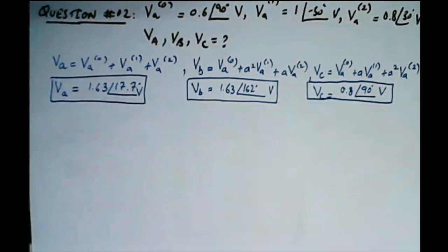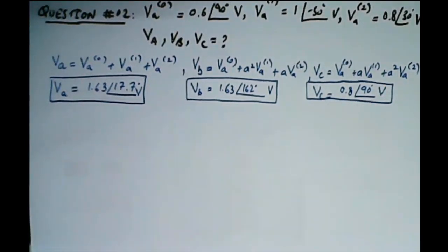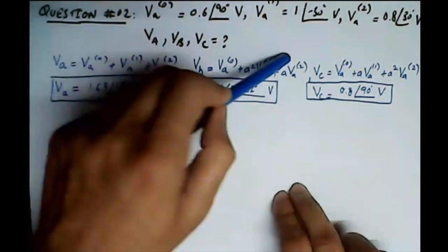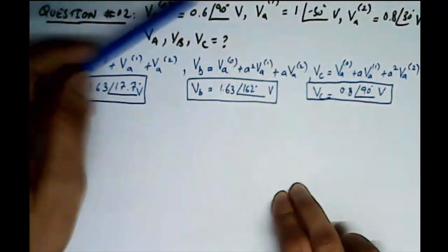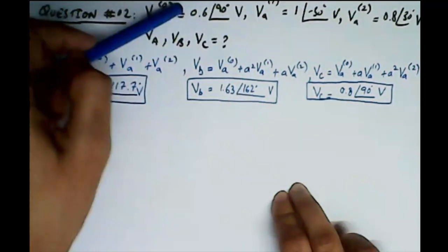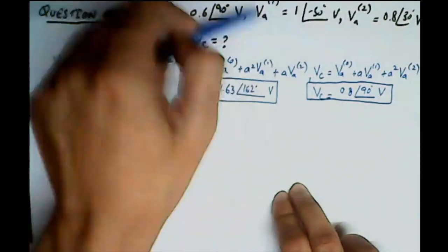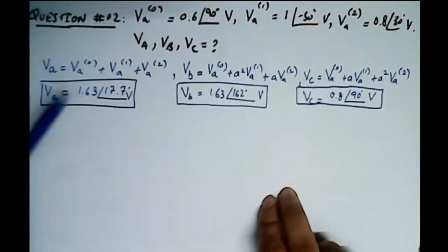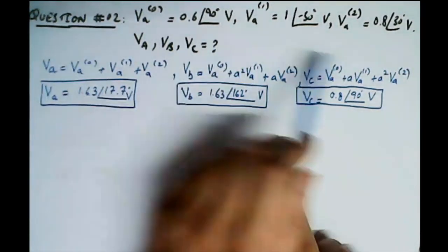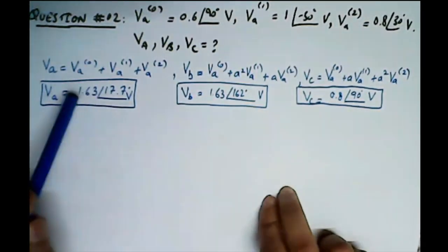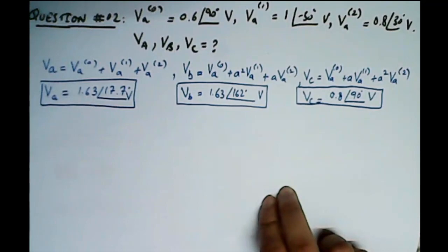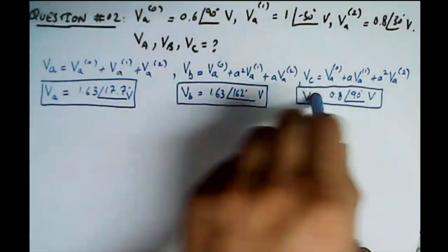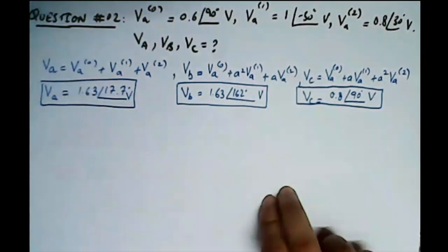One thing you will see is a further proof that when we add these symmetrical components, they were all symmetrical: zero sequence within them balanced, positive sequence balanced, negative sequence balanced. But when taking the phasor sum, these components are unbalanced. Magnitudes are 1.63, 1.63, 0.8. Angular separation is also not the same.